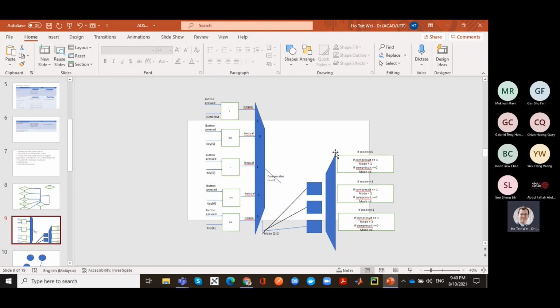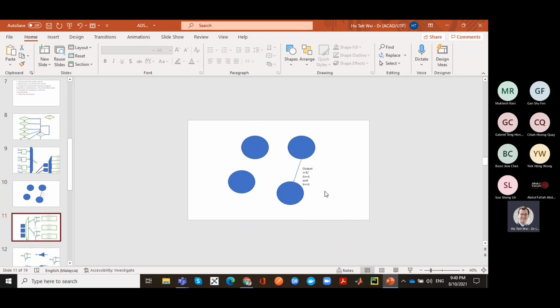So you have a state machine, which is basically nothing else but a hardware encoding of a sequence of modes. That means your circuit is just going to go into mode 2 first, then mode 3, then mode 1, then mode 4, then mode 5. That sequence of modes can be expressed as a state transition diagram, where each circle is a mode.